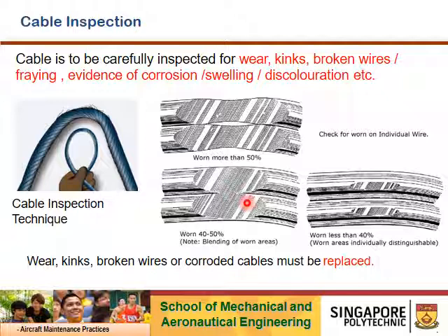But once you want to replace the whole cable run, it will be very tedious, because a lot of sidewall panels, roof panels, even galleys need to be removed. You have to actually remove a lot of items to access the cable. So when there are broken wires or corrosion, the cable must be replaced. This is a general statement, but refer to your maintenance manual again.